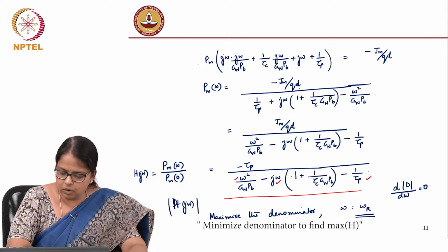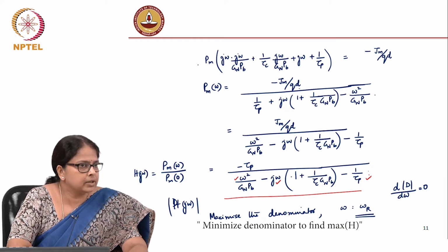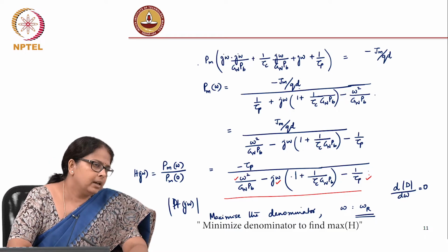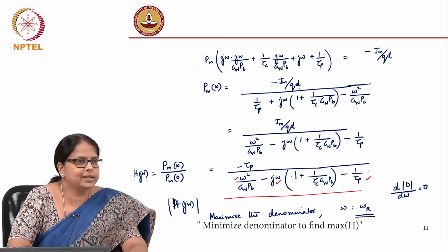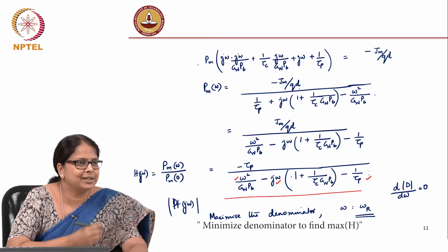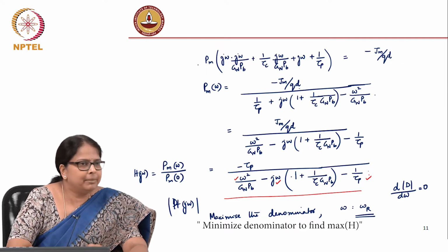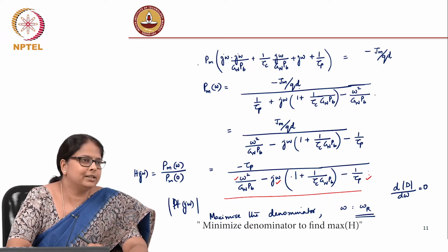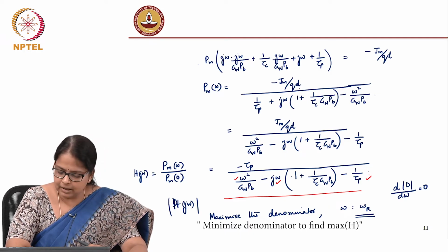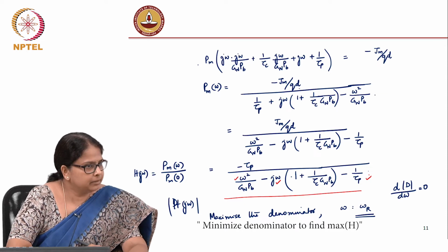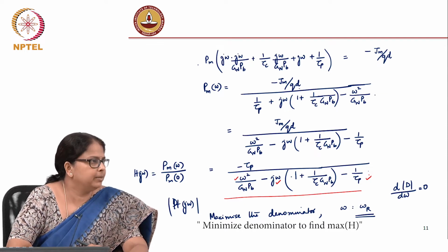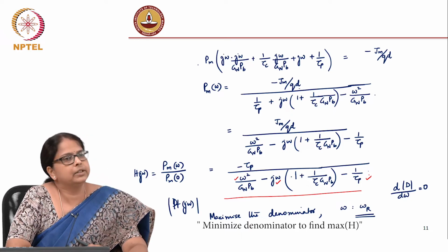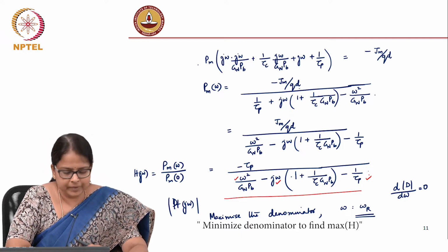Okay. So, we would like to know what is the resonant frequency of the system, and the quickest way, of course, you can do Laplace analysis on this to find the resonant frequency, what is the damping and so on, but the quickest way of finding the resonant frequency is to make sure that your denominator is at an extremum, by doing a first derivative of the denominator with omega.